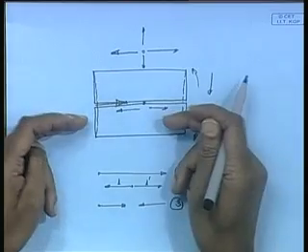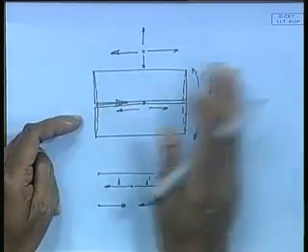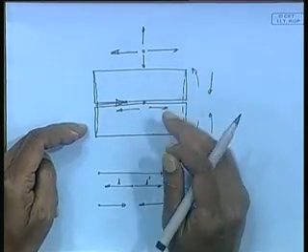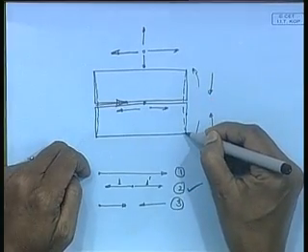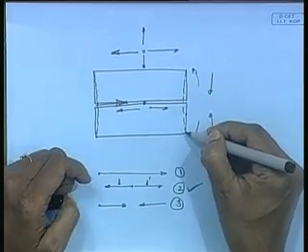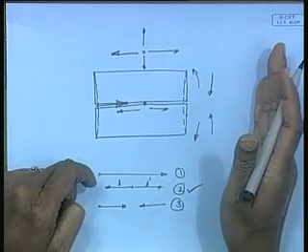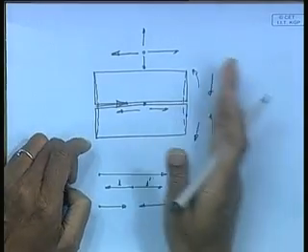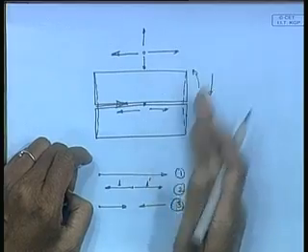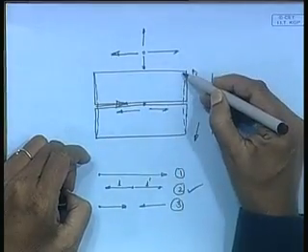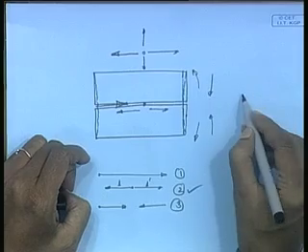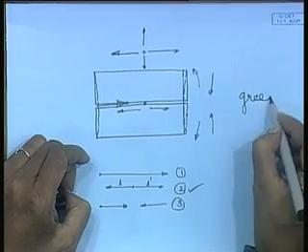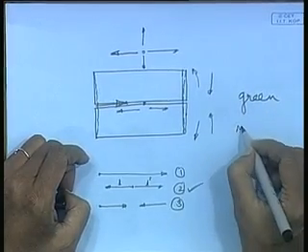But if I do the opposite, then the full thing may buckle, that will be more severe, because when something happens at the edge, I have some other means to take care of that. I can provide some allowance, so whatever shrinkage happens it still comes to the design dimension, or I can cut it off. I have additional material at the edges which is called green material.